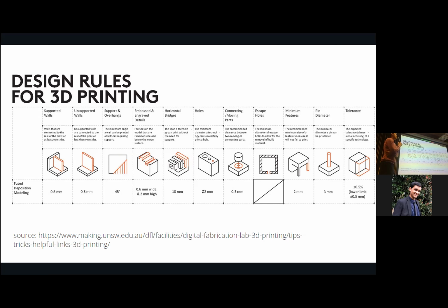Another rule is that when you have connecting parts, when you're fitting a part to another, just as we did with the key and the keyhole, right? Some of you might have made the dimensions exactly the same. Let's say 20 by 20 millimeters for the key and 20 by 20 millimeters for the keyhole. When you're actually printing, you wouldn't want to do that because it just wouldn't fit in properly. Usually, you want to have a gap, right? It says 0.5 there, but you can ignore that.